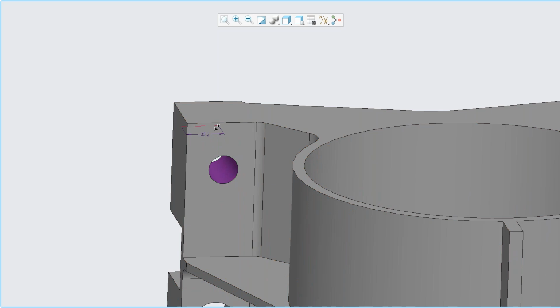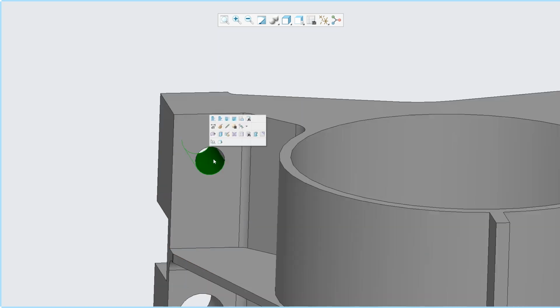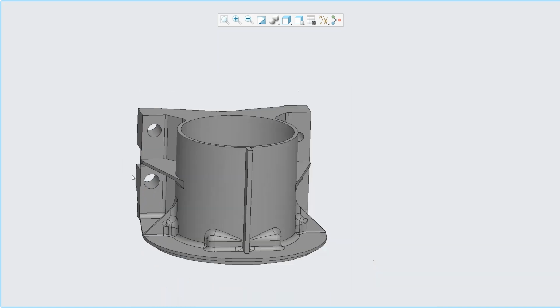These are my X and Y dimensions for the hole. And if I want to change the hole itself, the diameter of the hole, I can always do my modify analytic anytime, right? I know it gives a radius, but again, you do have the dimension to change that. So it's not just about dragging things and moving it around for concepting or for industrial designers.